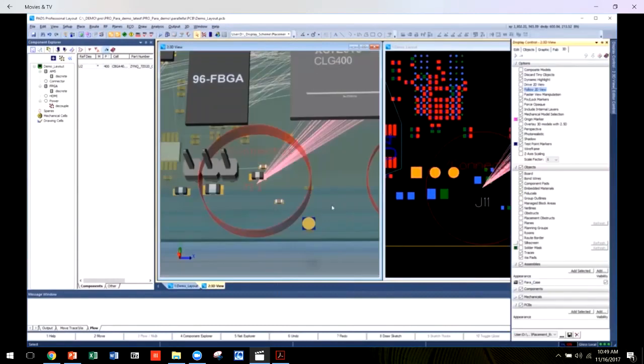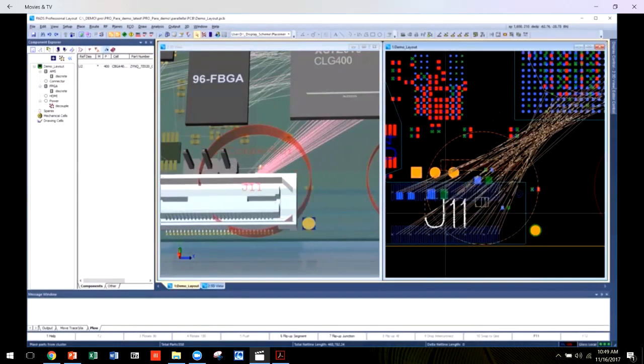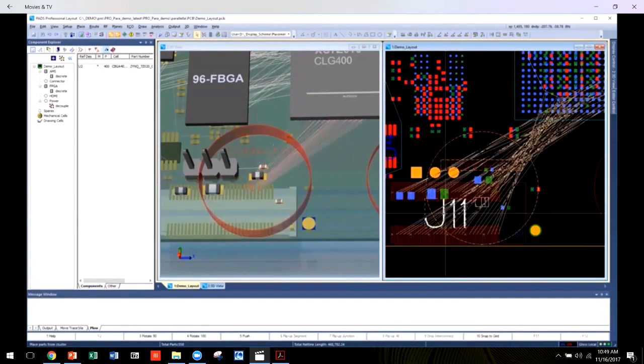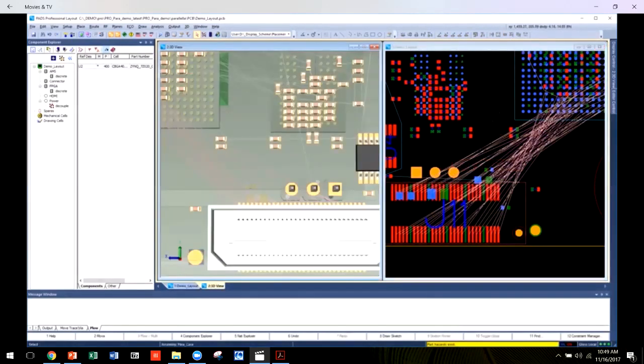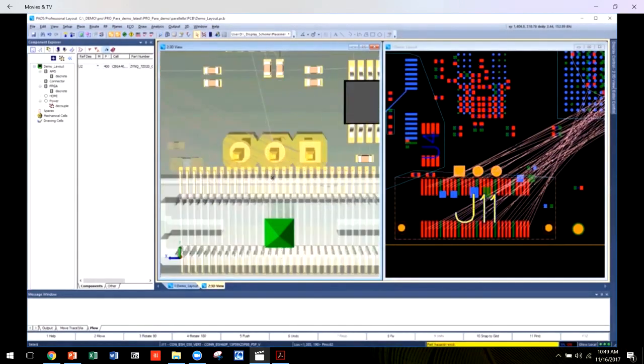While placing, view concurrently both the 2D and 3D representations of the part, and either drive or follow the 2D view while using 3D. Connector placement is especially helpful to view in 3D to make sure you get the orientation correct the first time. PADS Professional utilizes photorealistic solid models that can be used to verify component clearances when placing. The cell manufacturing drawing may not include all the finesse of the full 3D model, and it can be difficult to quickly visualize the orientation of a component.